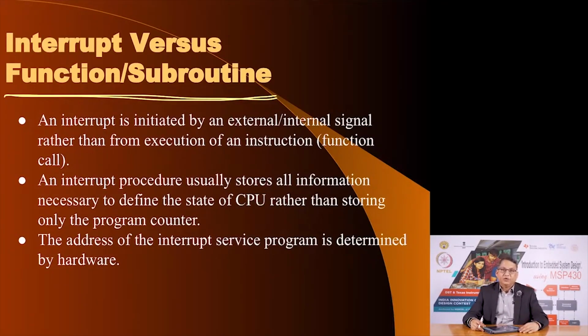In a normal subroutine, you of course suspend your current execution and go off to execute that subroutine, but after the subroutine is finished, you want to come back to where you were earlier. The way to do that is to save the program counter value onto the stack.